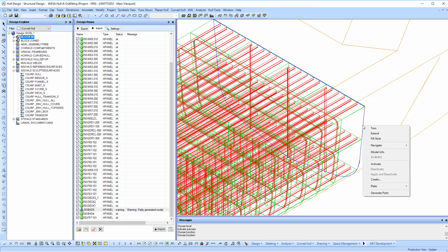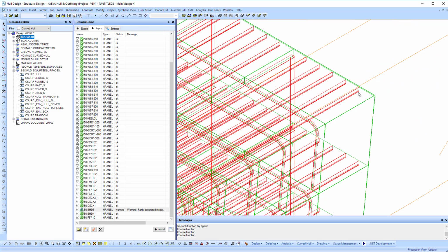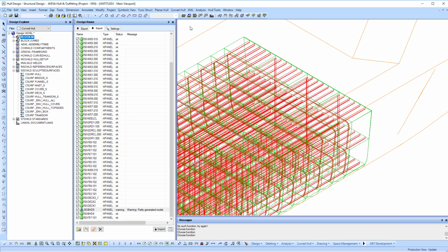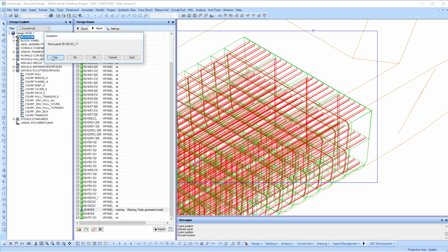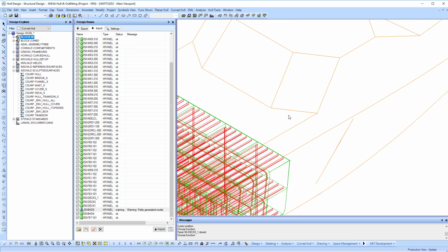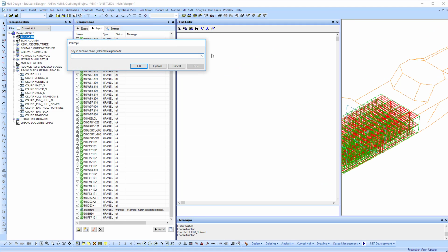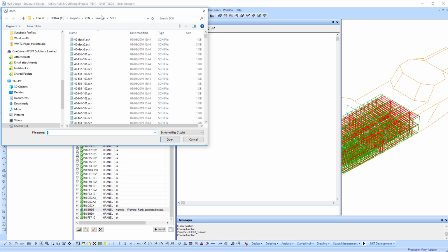I know from previous cases of running this example that this particular bulkhead here, bulkhead 5, does not have the stiffeners that I expect. And an investigation led me to find out that what I need to do is a regeneration of the deck to which these stiffeners are attached and bring in the stiffened bulkhead again. We'll bring this bulkhead in simply as a scheme file because that's just an individual file. We don't really need to go through the whole design reuse process again.